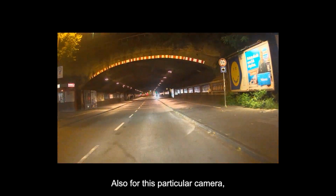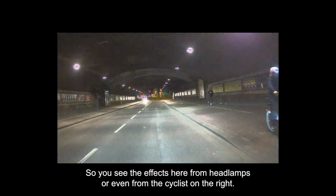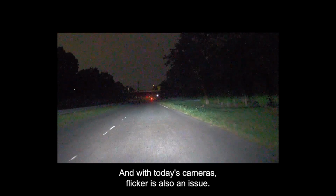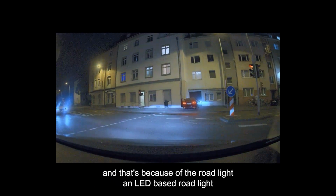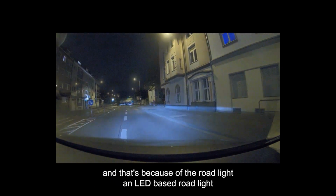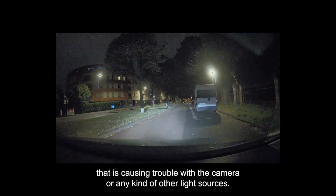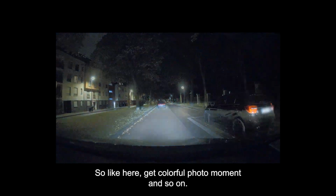Also, for this particular camera, headlights and strong light sources are an issue. So you see the effects here from headlamps or even from the cyclist on the right. And low light, of course, always a problem. Here under the bridge, there's not so much light, but we still need to know where to go. And with today's cameras, flicker is also an issue. You see here, the whole scene is flickering. That's because of the LED-based road light that is causing trouble with the camera. Or any kind of other light sources. So like here, it gets colorful for a moment and so on, a lot of things going on.